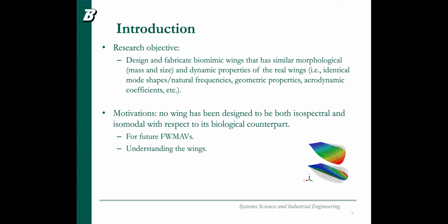So for our research, our objective is to design and fabricate biomimetic wings that have similar morphological and dynamic properties to the real wings. Morphological means mass and size, meaning similar weight and similar dimensions. And also the dynamic properties: we're trying to get wings that have identical mode shapes, natural frequencies, geometric properties, aerodynamic